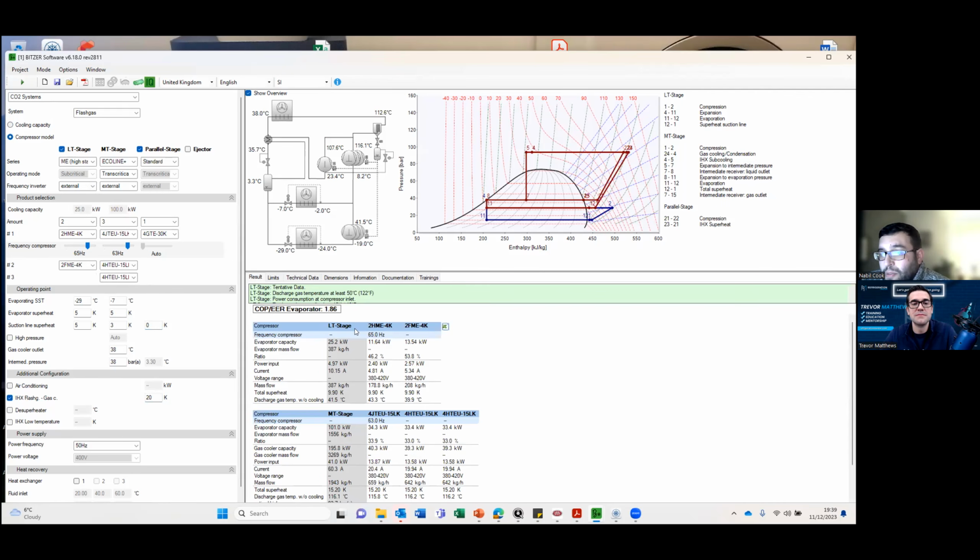And wow, look what's happened to our design COP. Huge. It's gone up 1.66 from 1.51, I think it was. Well, it was 1.51 first, then we went up to 1.66, and now we're up to 1.86. And that's an incredible result. Now, as we discussed, we don't spend much time per year operating this. So we have to start thinking, well, what does it do lower down?